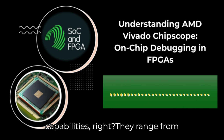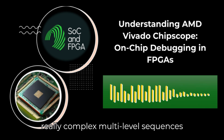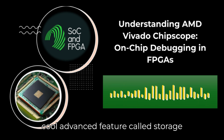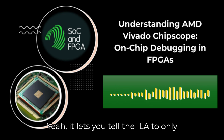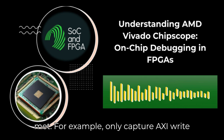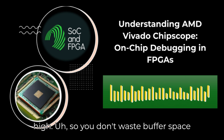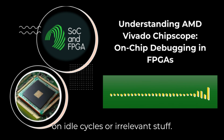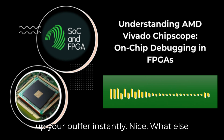And its trigger capabilities range from simple level or edge detection up to really complex multi-level sequences using Boolean equations. And it has this cool advanced feature called storage qualification. It lets you tell the ILA to only store data when some other condition is met. For example, only capture AXI write transactions if the debugging signal is high. So you don't waste buffer space on idle cycles or irrelevant stuff? Precisely. It's super efficient for capturing sparse events without filling up your buffer instantly.